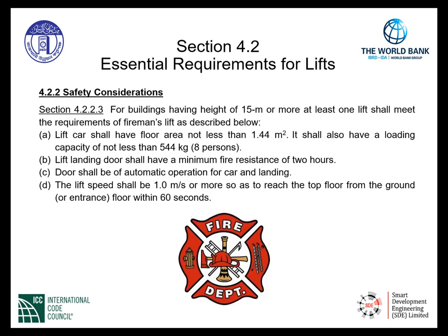Section 4.2.2.3. For buildings having height of 15 meters or more, at least one lift shall meet the requirements of fireman's lift as described below. The following indicates specific requirements for the fireman's lift. Item A. Lift car shall have a floor area of not less than 1.44 square meters. It shall also have a loading capacity of not less than 544 kilograms, approximately 8 persons.